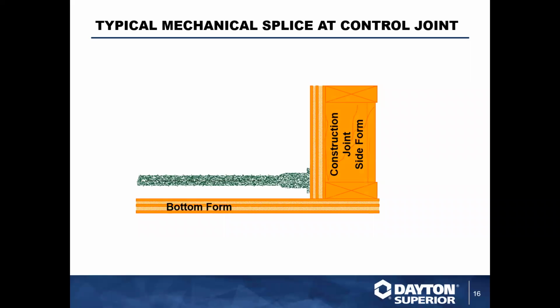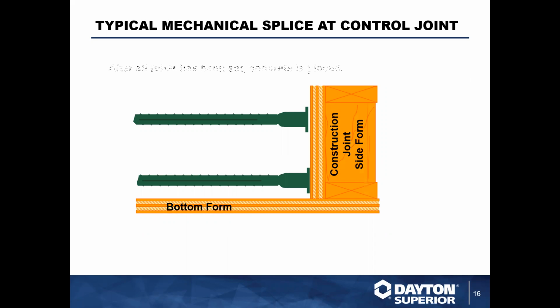Now, typically when we're talking about a construction joint system to put in place on most job sites here, the Dalbar system, basically you take your DB and attach it to your formwork. There are holes in that flange running around the outer edge, and you can drive a nail or a screw through there to attach it to your wood form.